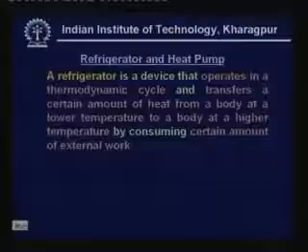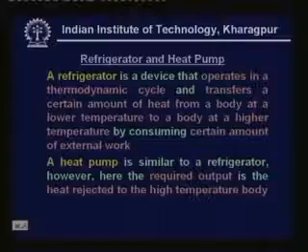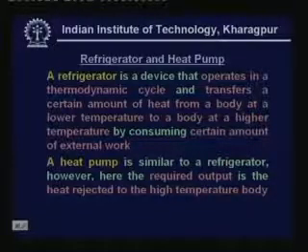Now a heat pump, hardware-wise, is exactly like a refrigerator, but the difference is that in a refrigerator we need a cooling effect, whereas in a heat pump we want a heating effect. That means in a heat pump we are not interested in the heat extracted at the low temperature level, but we are more interested in the heat rejected at the high temperature level. So from a practical application point of view, a refrigerant system can be used for summer air conditioning, whereas a heat pump system can be used for winter air conditioning.